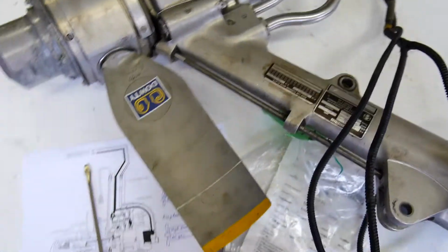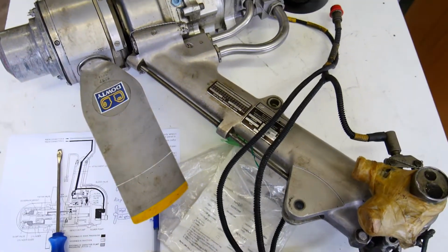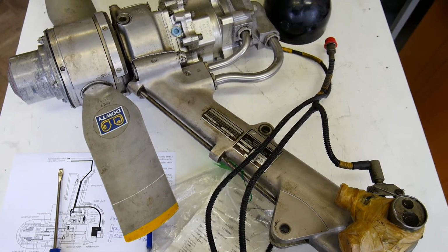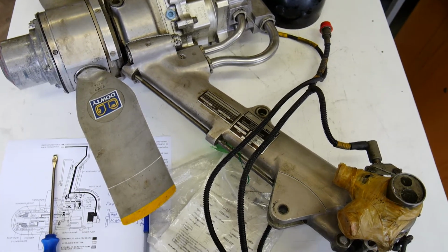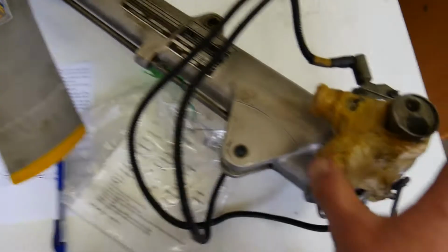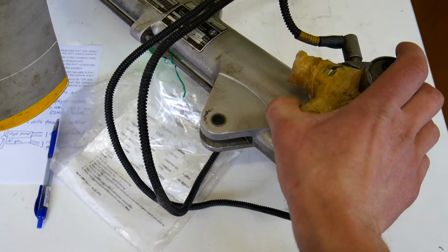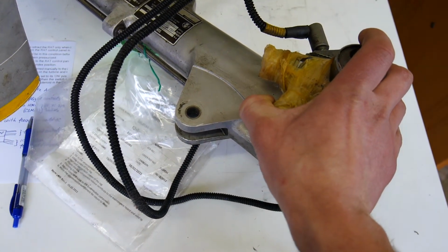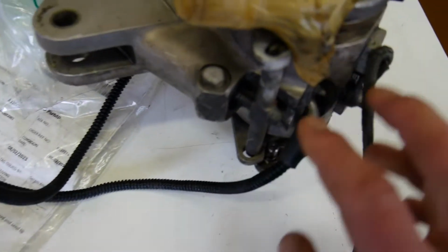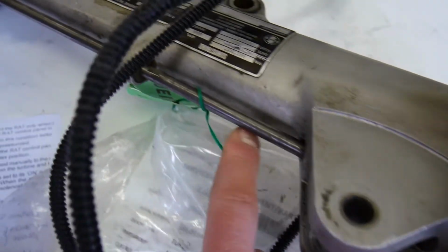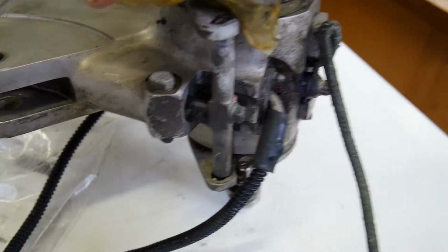It becomes deployed automatically when we lose electrical power, AC power, or when we fully lose hydraulic power and there is no electrical power to generate hydraulic power. Then it starts to be opened by means of the actuator, which is attached here. When it opens, this will rotate. It has a mechanism which is connected with the index rod.